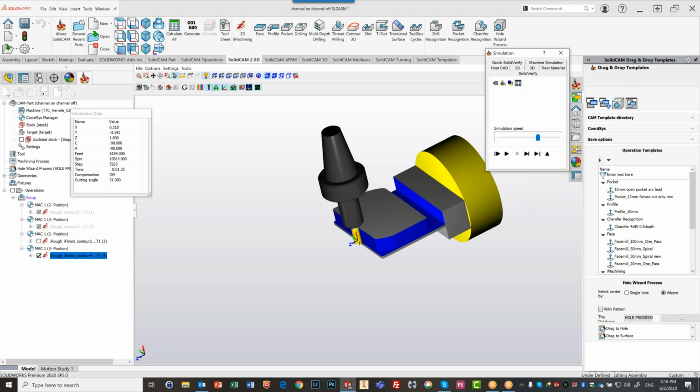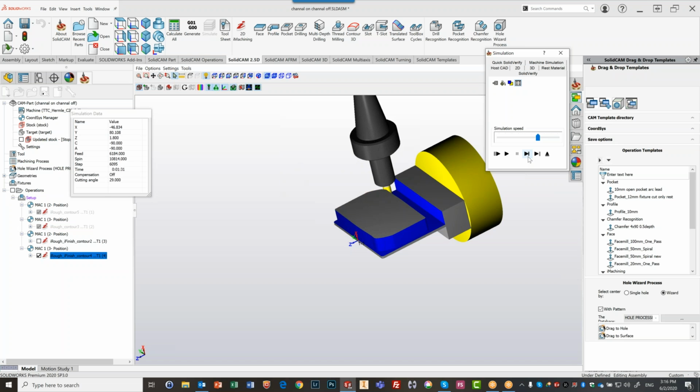Your conventional milling. No, that's just because of the amount of speed. It's going fine. It's not conventional milling, it's actually climbing. I'll slow it down. That's not the problem. The problem is like this, on the machine right now. This floor, once it flips around, becomes... There is a vibration problem, no? Yeah, exactly. Got rid of most of the material.